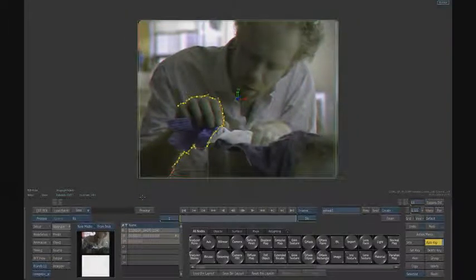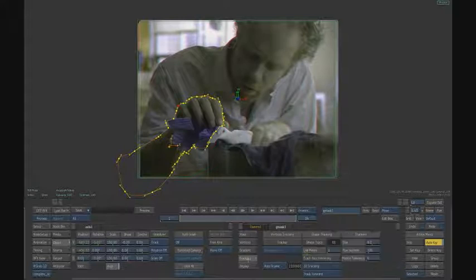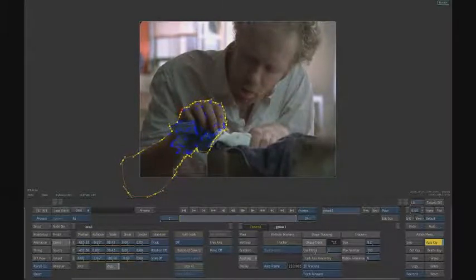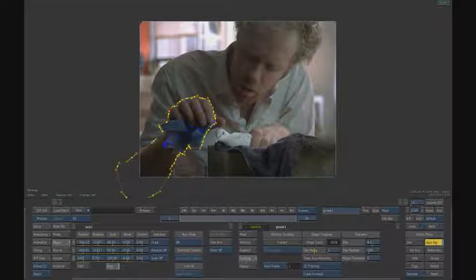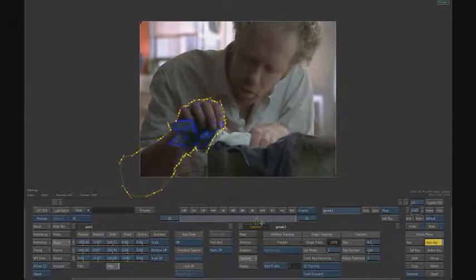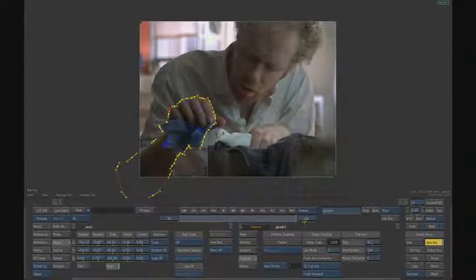We also have a new tracker that I wanted to show you called a shape tracker, which actually does a planar analysis and essentially picks hundreds of points within a scene like this to generate a result to follow this movement. So if I just take my mask here, go down to the tracking tab and hit shape track, what you'll see is it's going to do an analysis picking essentially the content that's good, which is really in the middle, not around the edges, and essentially that movement that is inherent in this shape.